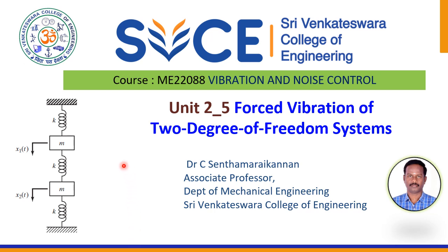As you can see in this diagram, we have a classic representation of a 2 degree of freedom system. We have two masses, each denoted by m, and three springs, each with a stiffness k. The displacements of the masses are represented by x1(t) and x2(t), indicating that they are functions of time. This setup allows us to analyze how vibrations propagate through the system and how external force can influence the motion of each mass.